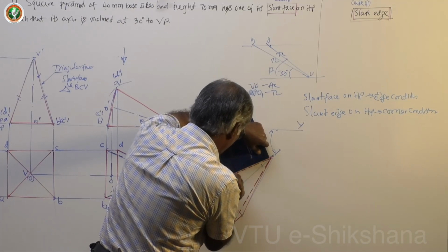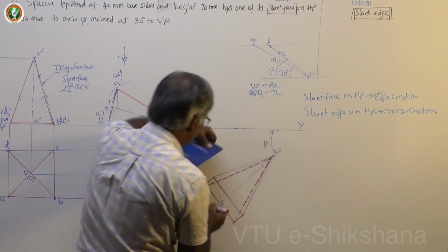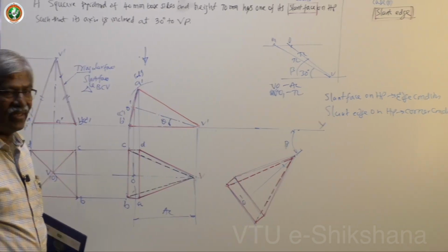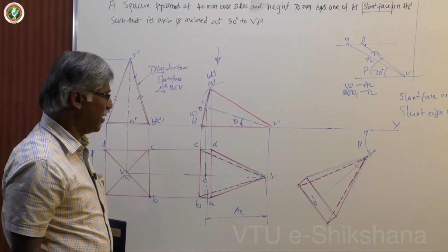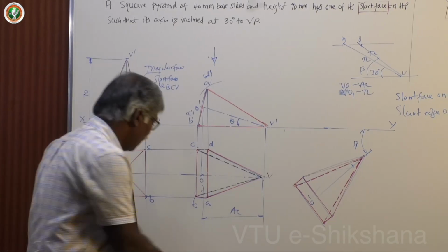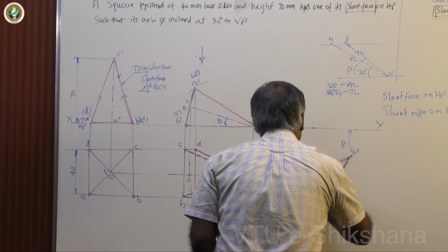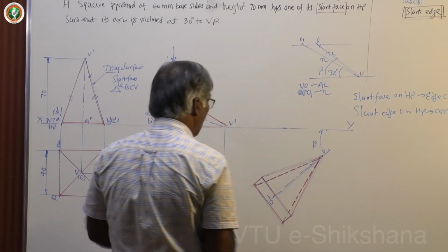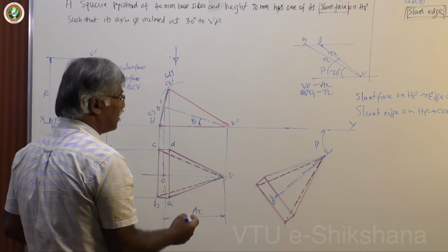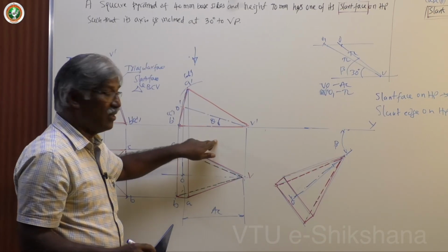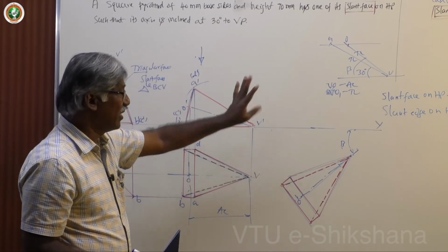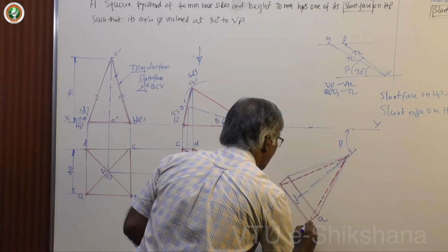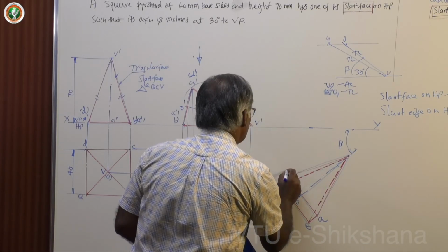Because of less number of sides we can do it, otherwise it becomes clumsy or number of lines will coincide and then give something else. Now keep this axis reference, this is O. Now project all this. The first thing is you have to find beta. Suppose if he says appears to be, then take directly. Now name these points carefully, A, B, C, D.